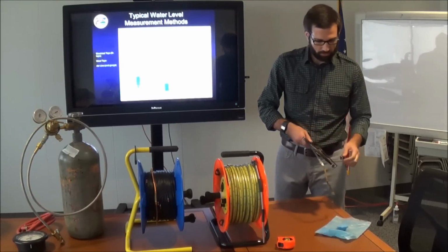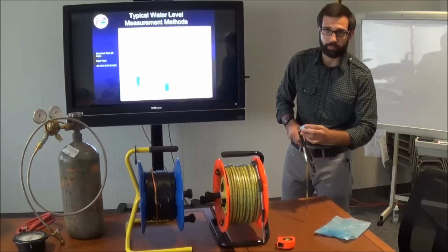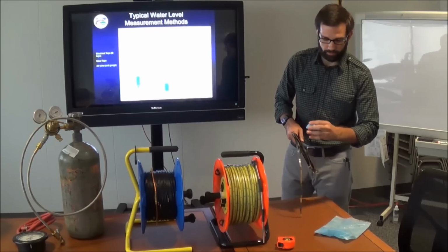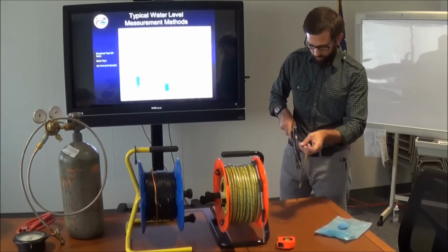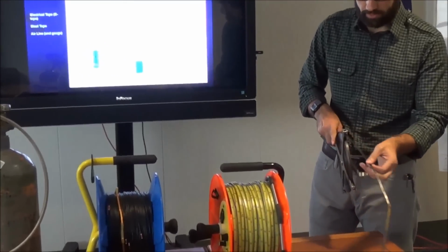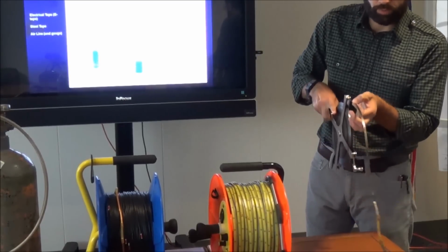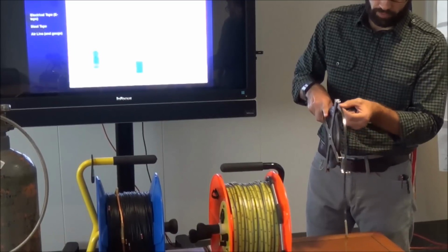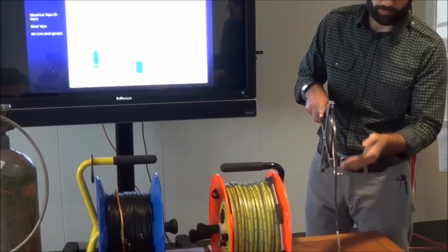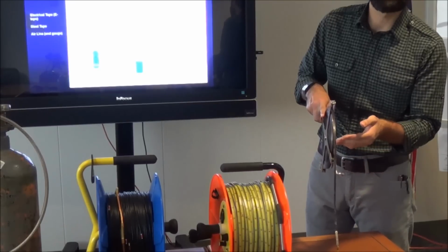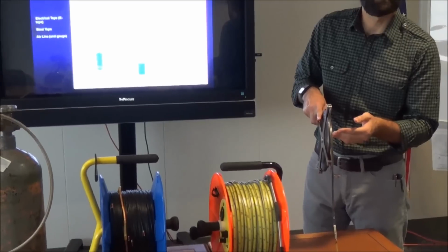And what you do with this sort of tape here is you take the chalk, you mark it on the end of the tape here up to a certain footage, probably about 5 feet. You send that down the well, and then at some point where you think your water level is close to it, you grab, dip to the well, and then pull up. And so you know where your hold is here. Let's say it's 50 feet, and we know when we pull this up that about 2 feet of the chalk came off. So our water level is 48 feet below our measuring point there.